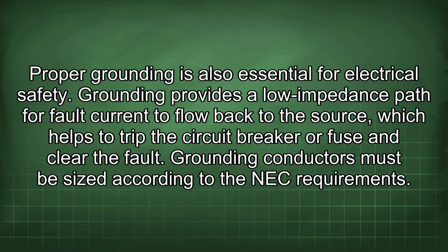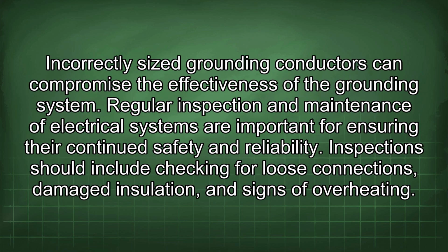Proper grounding is also essential for electrical safety. Grounding provides a low impedance path for fault current to flow back to the source, which helps to trip the circuit breaker or fuse and clear the fault. Grounding conductors must be sized according to the NEC requirements. Incorrectly sized grounding conductors can compromise the effectiveness of the grounding system.